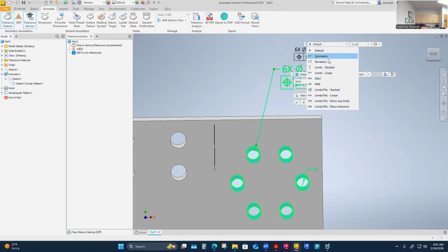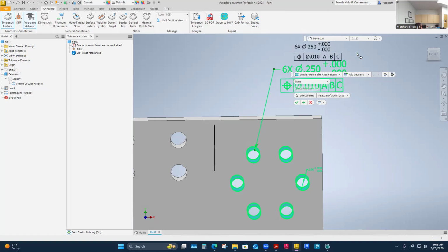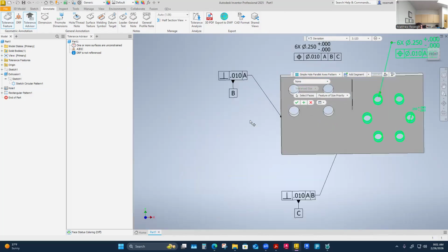Do we want to draw out the zeros because of the 3125? Oh, when I get over to that one, I'm just going to hold 4 decimal places. So I'll hold a 4 decimal place tolerance. Yes, I'll still hold the same only on that one. Yeah, it's getting low, and that's arguable. I'm just going with my ASME standard, which is when the dimension is holding a certain decimal place, my tolerances are going to hold those same decimal places. I'd have to look this up. I remember mentioning this the other day, and I never did look it up yet. But I'm just going to go with my best guess, which is to hold tolerances to match my decimal places, even my geometric tolerance here.